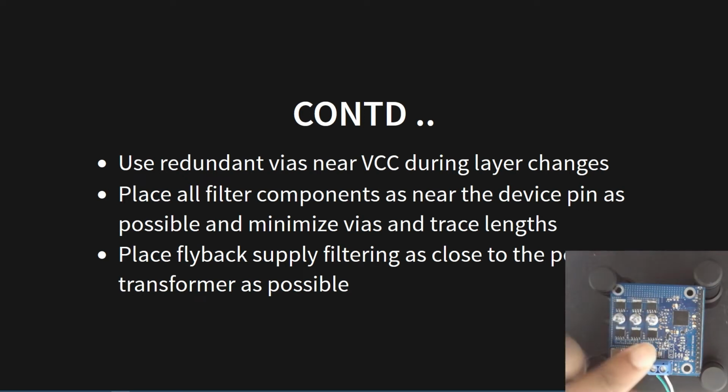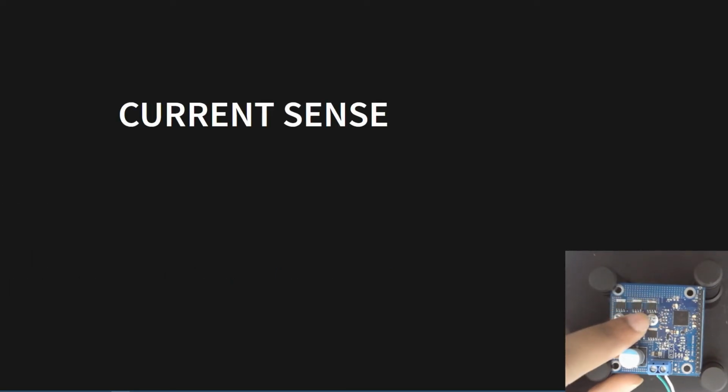So if there's a power transformer powering this, I would have to put some filtering, depending on how you're powering this board. Based on that, I would have to add a filtering capacitor closer to this. Now, this will be on a drone, so how am I going to power this whole thing? That's something I would have to consider when I'm actually deploying it onto the main system.